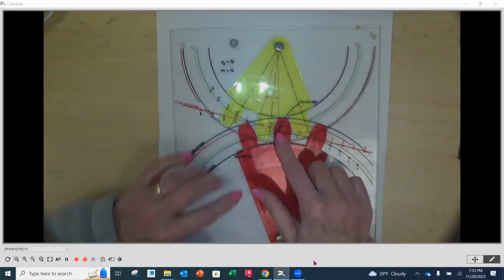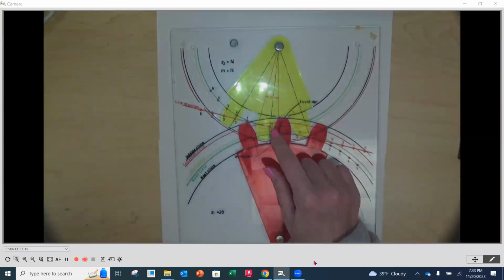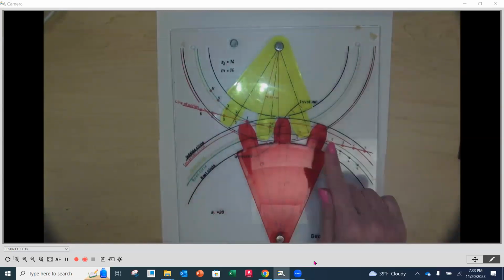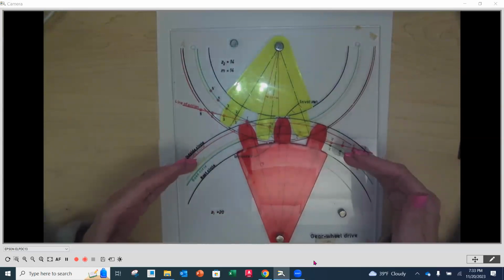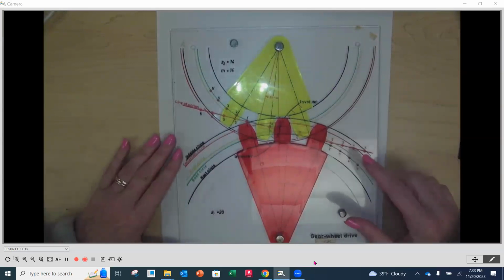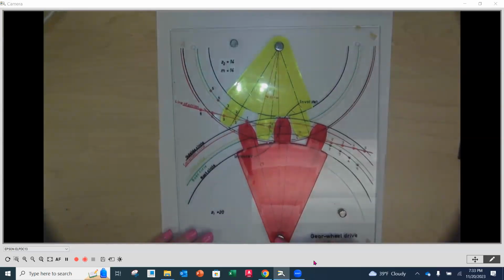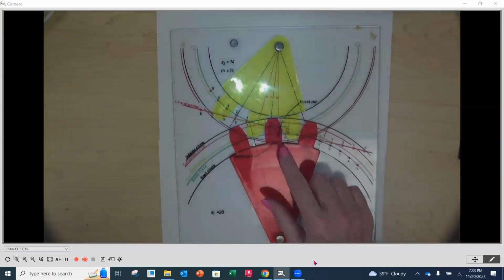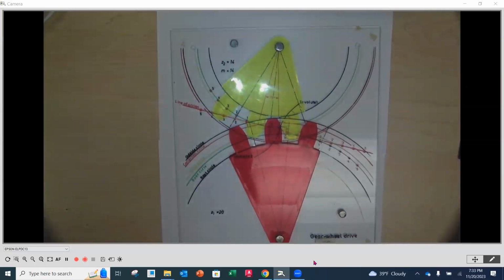And if we line that up here, that's the point of engagement on the two teeth that come together. So the pitch circle is going to be here for the top one. The pitch circle is going to be here. That's the pitch diameter, okay? A lot of times we hear it called the pitch circle, pitch diameter. And then their center of rotation is going to be at the center of the gear. And where they actually hit is going to be that actual point, what we call effective diameter, okay?